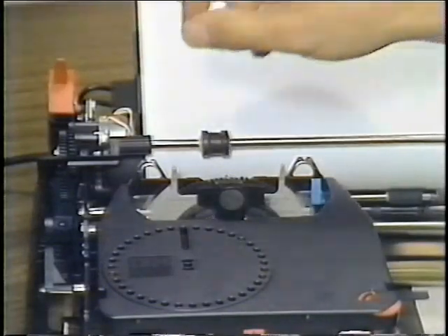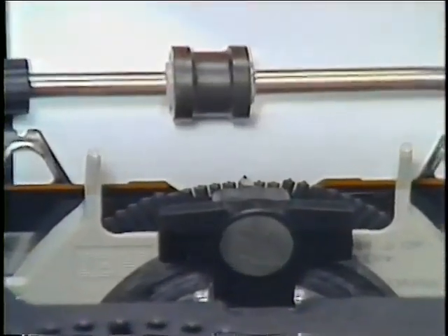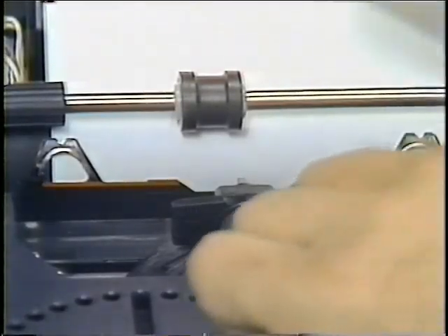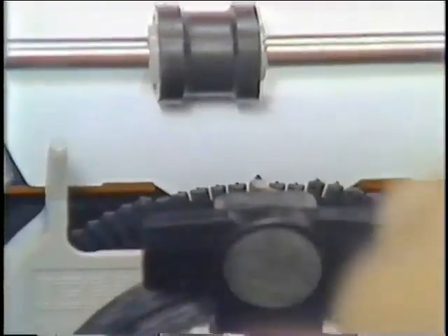Let's see how the homing LED and homing sensor operate. The homing LED is mounted on the rear of the carrier frame and emits a light which is aimed directly at the homing sensor. This light is infrared and cannot be seen. The homing sensor reads the home position, the pitch, and the impression level of the print wheel by sensing the holes in the print wheel. Print wheel homing and the reading of the pitch and impression levels of the print wheel takes place during power on reset, and when the first character is typed after a print wheel change.